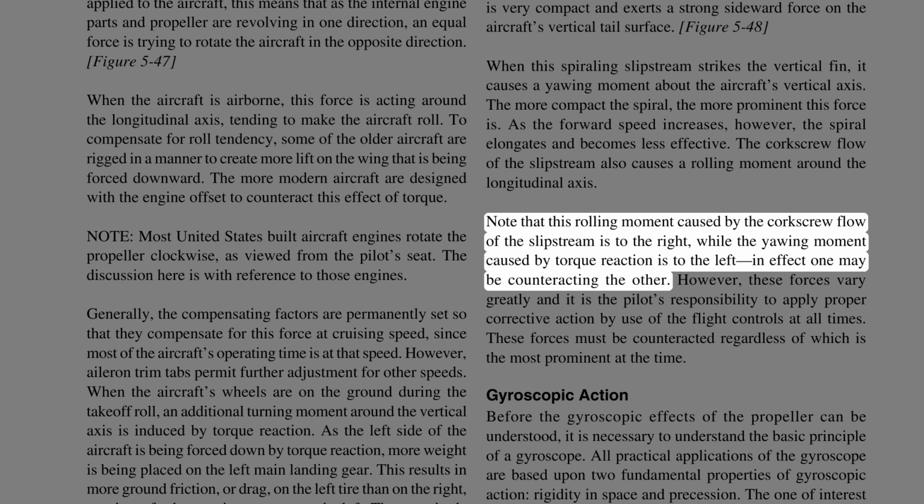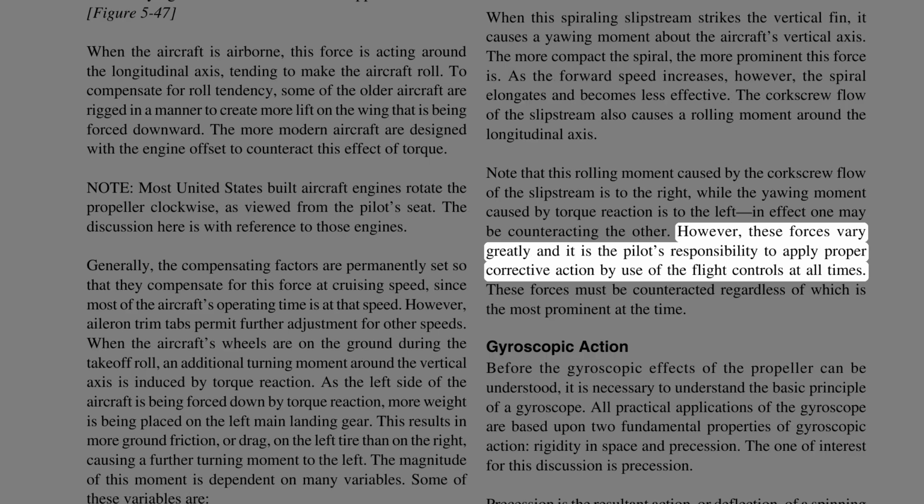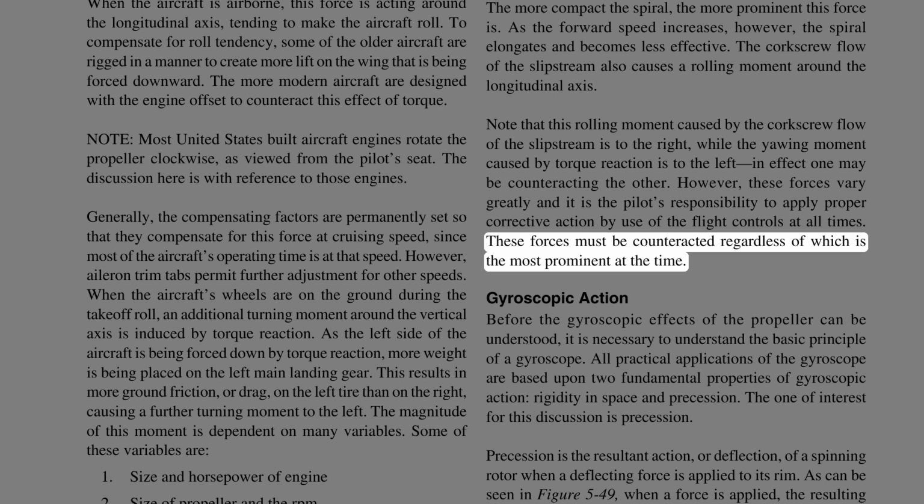Note that this rolling moment caused by the corkscrew flow of the slipstream is to the right, while the yawing moment caused by torque reaction is to the left. In effect, one may be counteracting the other. However, these forces vary greatly, and it is the pilot's responsibility to apply proper corrective action by use of the flight controls at all times. These forces must be counteracted regardless of which is the most prominent at the time.